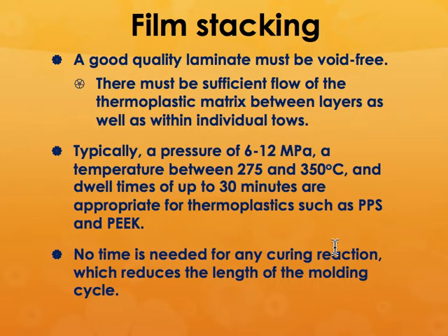When you stack these materials, a good quality laminate has multiple layers. A single layer is called a lamina, multiple layers are called laminae, and the whole composite itself after consolidation is called a laminate of this composite material.